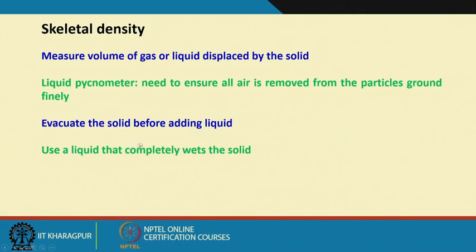Do not get confused with the bulk density, because here you have to take extreme precaution to remove the entrapped air. Or use a liquid that completely wets that solid, that means there is no chance that there will be any entrapped air.